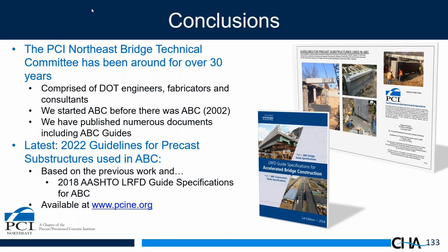Grouted couplers are not the only option. I know a lot of the seismic states are not keen on grouted couplers, and I get it. I don't have a problem with that. But I mentioned those socket connections and some of the pocket connections we showed are perfectly adequate for high seismic regions. And the guide specification has design provisions for those capacity protected and strength design connections using those details. So we have specifications to cover that.